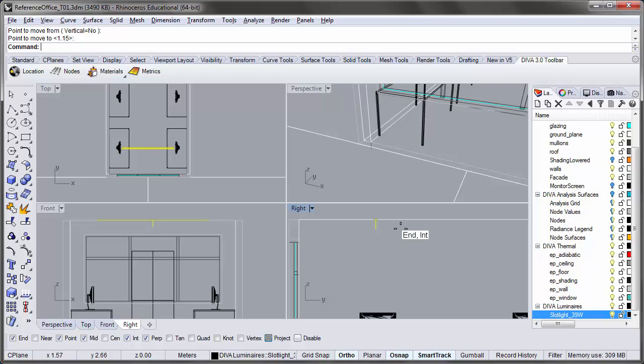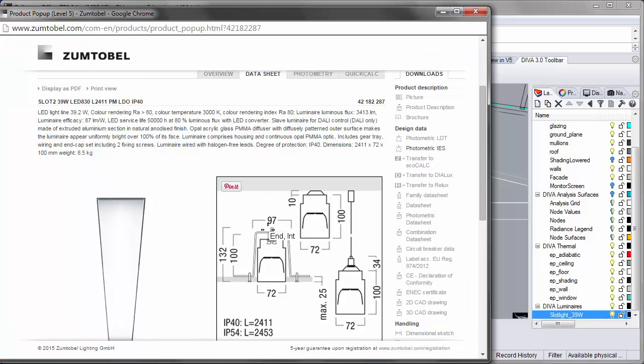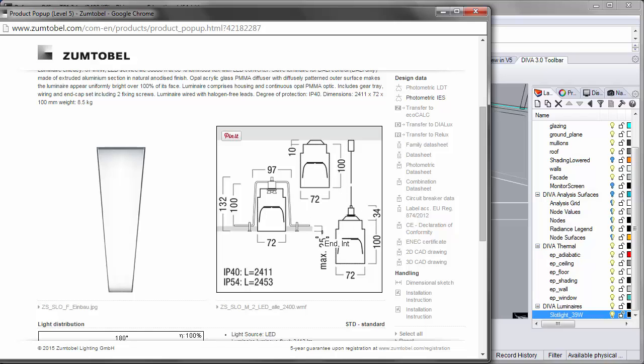And if you remember from the product data, you'll see that from the housing there's a few different ways to actually incorporate the light fixture. We can have it recessed with the ceiling, in which case I would have to create an opening in the ceiling, or maybe just lower the light fixture a tiny bit off the ceiling so that it's not coincident with the ceiling plane. You'll see that there's a surface mount option that is 100 millimeters off of the ceiling, or 110, and then there's a pendant mount option that you can hang the light fixture from, a distance as long as your cable allows, that drops it from the ceiling.